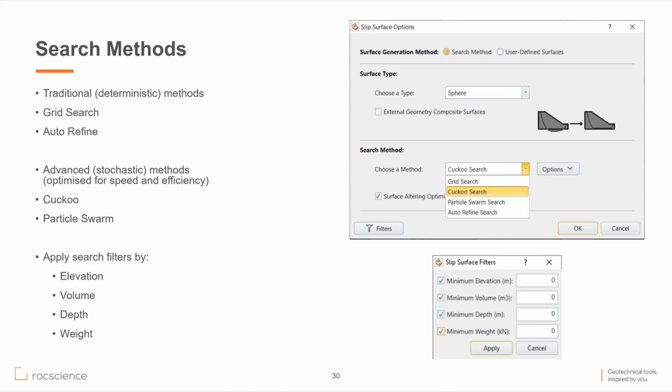What properties data do we need? So for Slide 3, it's exactly the same as Slide 2. What material properties for your rock mass, weak planes. If groundwater is affecting your stability analysis, you need to have that as an input as well.